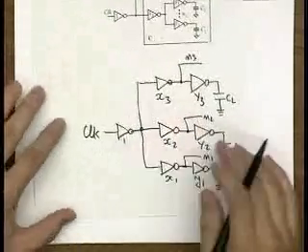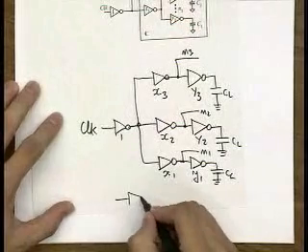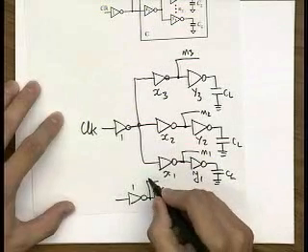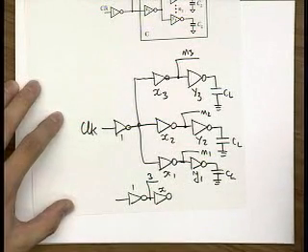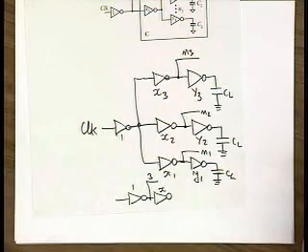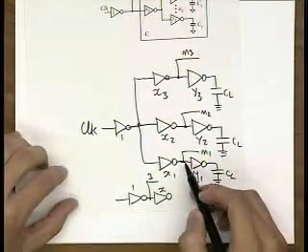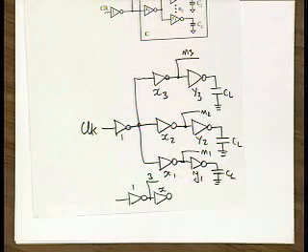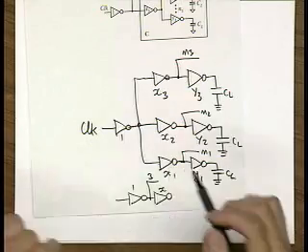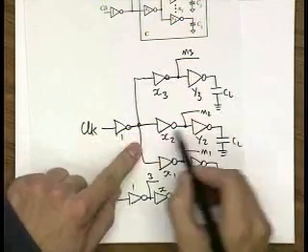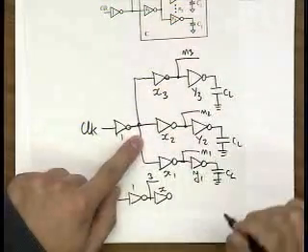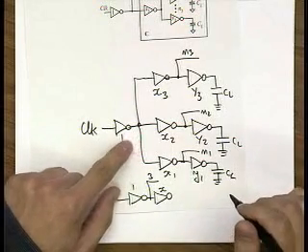So if you develop a model over here and say, I have my clock buffer size 1, then some x's are all equal, and then you have a branching factor of 3, that's not correct. That's not going to give you a good answer, because the problem with this branching is that once you have this off path, you no longer have control over what's going to happen to the delay of that path. You just forget it. That's some fixed capacitance sitting there. I don't care about this delay. But in this case, I do care, because I have this off path over here. If I just analyze this path individually, then I have this off path that has to have the same delay as my critical path. So make sure you include that in your analysis.